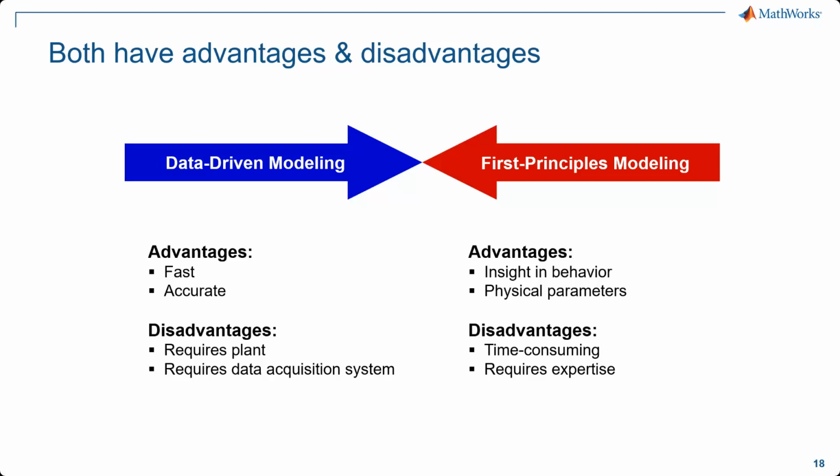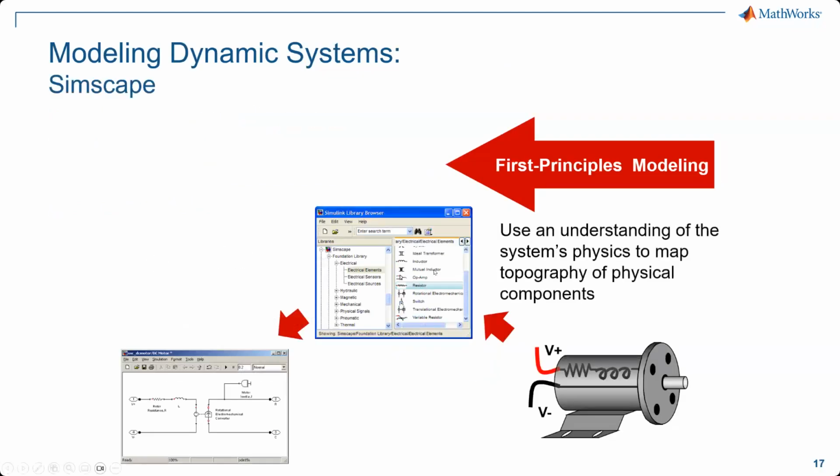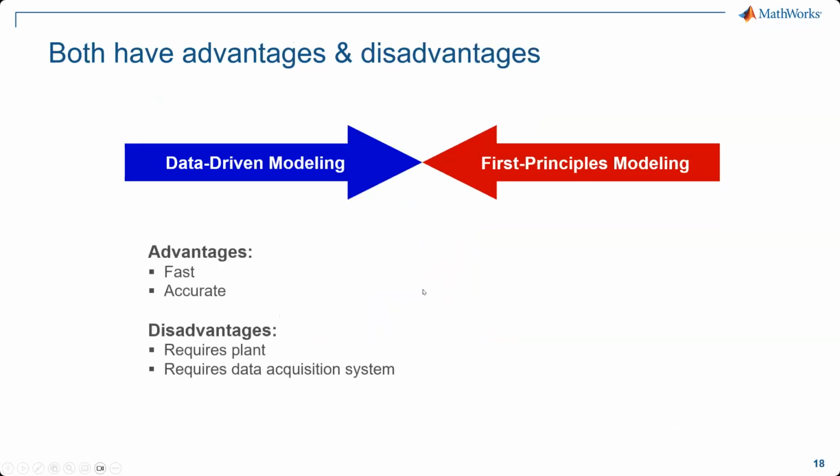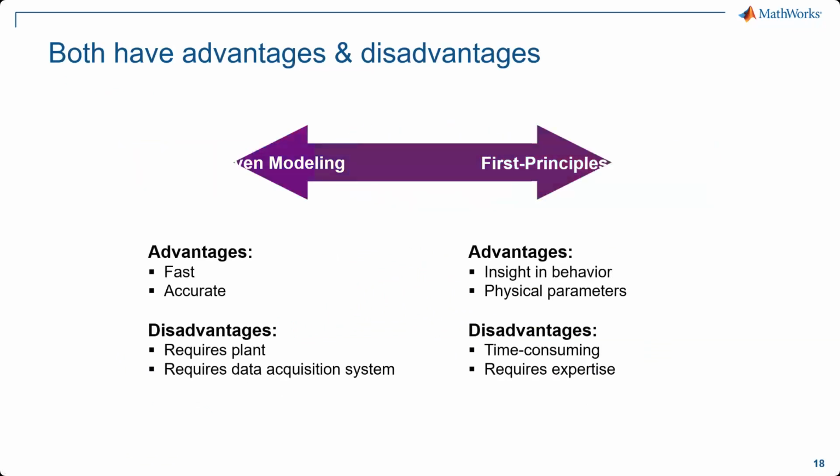So now, having known this advantage and disadvantage, you can also utilize the Simscape way, where the physical components are available. For example, your voltage source, inductor, and resistance. And in this case, you don't have to worry about the physics equations, and you can directly model your DC motor using these discrete components like inductance, op-amp, and resistors. Hence, utilizing either of these two methods, I will create some kind of model equation, which I have already developed, but there is one step left.